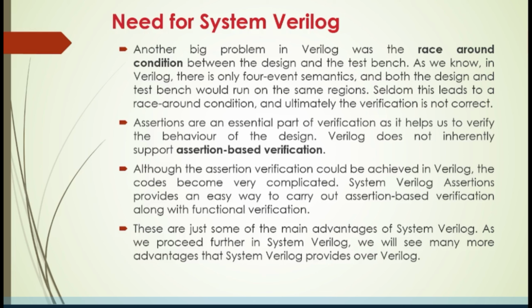You can write the assertions in Verilog. Inherently, assertion based verification is not supported in Verilog. Okay, but you can write some type of assertions in Verilog, but these assertions will make the code very complicated. You can't write it very easily in Verilog, right? So in order to avoid all this, SystemVerilog has a very easy way of writing an assertion, an easy way to check the behavior of your circuit. This is also one more advantage.